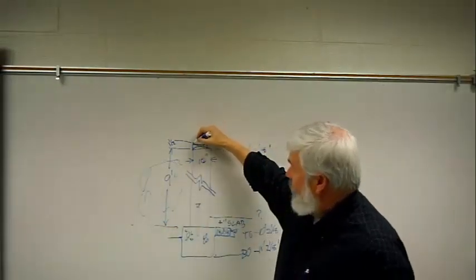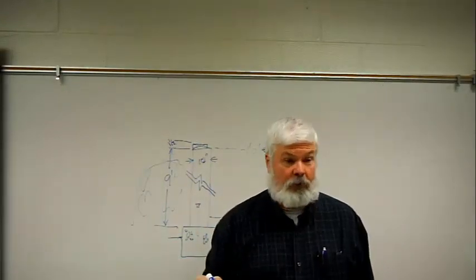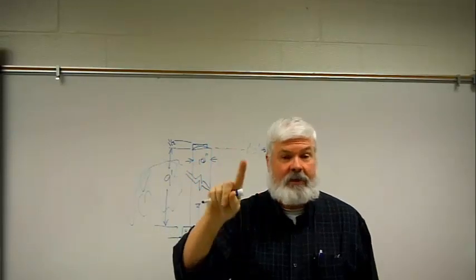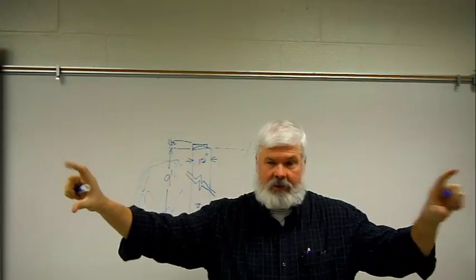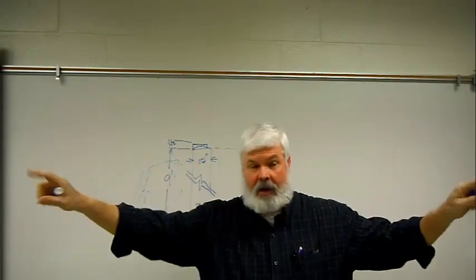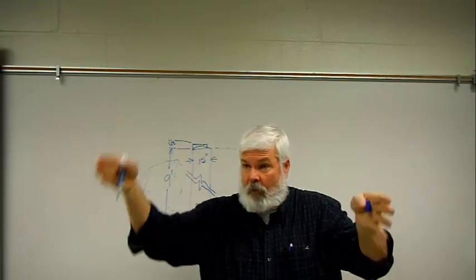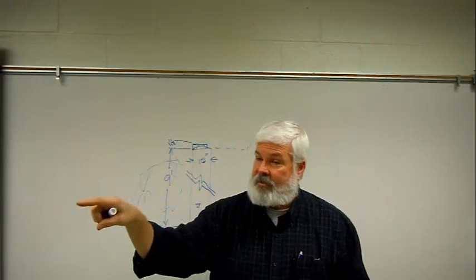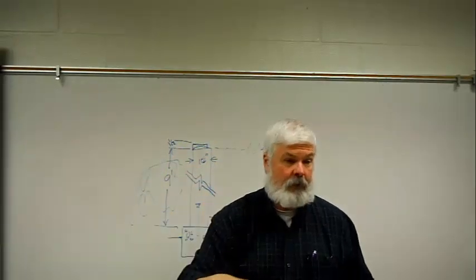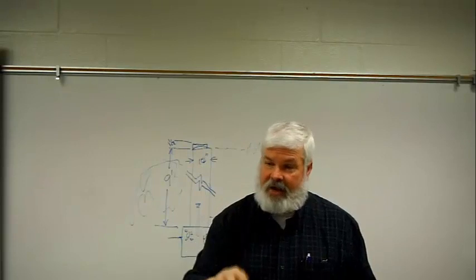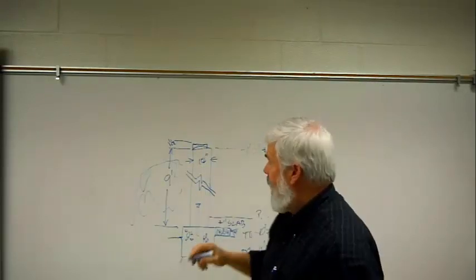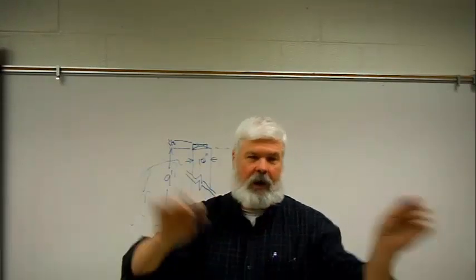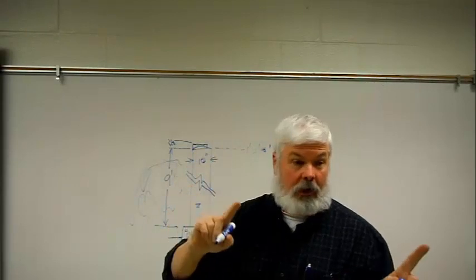So there are a lot of different types of joists for a floor system. Two of the most typical are, well, three: 2x10s, shorter, smaller spans; 2x12s, you can get a bigger span and still carry a load out in the middle between one bearing point and another; and I-joists, which are engineered lumber. The way I'm having you set up your Revit template is for an 11 7/8 inch I-joist. And the reason it's 11 7/8 inches instead of 12 is a story that I won't get into, but it actually is totally logical.